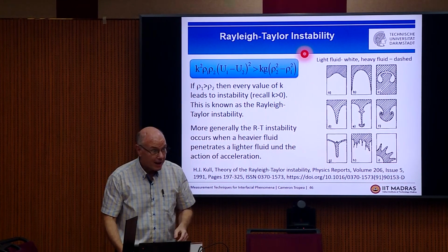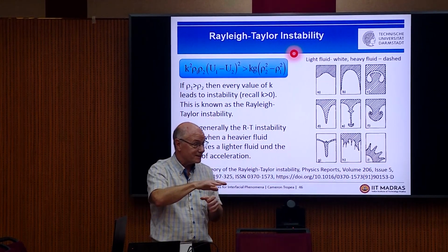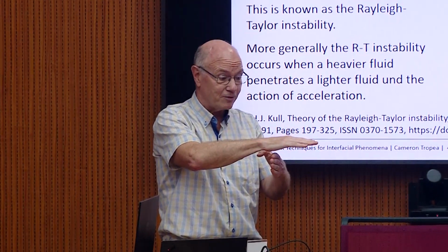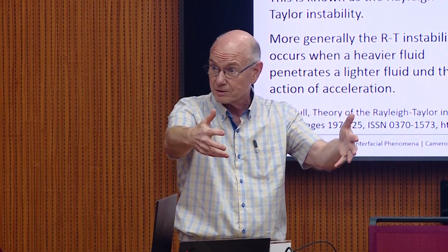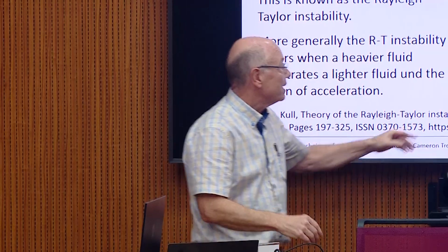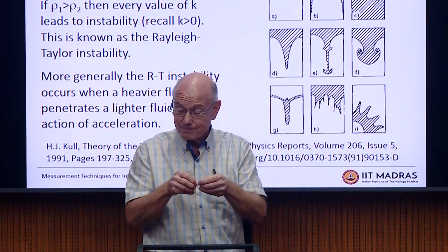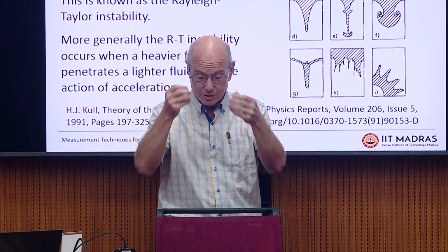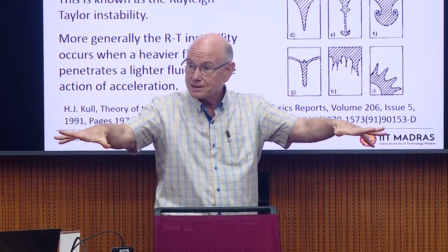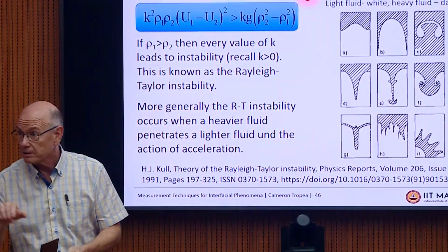However, even if you have an acceleration not due to gravity but due to something else, so if you have a heavy fluid here and for some reason it's accelerating against a light fluid, for instance it's rotating, so you have a centrifugal force, then it will break through the heavy fluid into the light fluid, exactly the same. And so you can get all kinds of fingering if you have a droplet spreading out into air. It impacts and starts to spread out. You have a heavy fluid accelerating into a lighter fluid, Rayleigh-Taylor instability, and you get fingering.